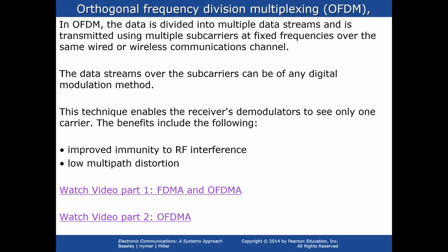So in OFDMA, we employ a more complex kind of guard period called the cyclic prefix, in which the end part of a symbol is transmitted in the preceding guard period. It also ensures orthogonality between the subcarriers by keeping the OFDM symbol periodic over the extended symbol duration, and therefore avoids intercarrier and interchannel interference simultaneously. Since OFDMA uses composite IFFT samples, the cyclic prefix is added by taking some samples from the end of a symbol period and placing them at the beginning.